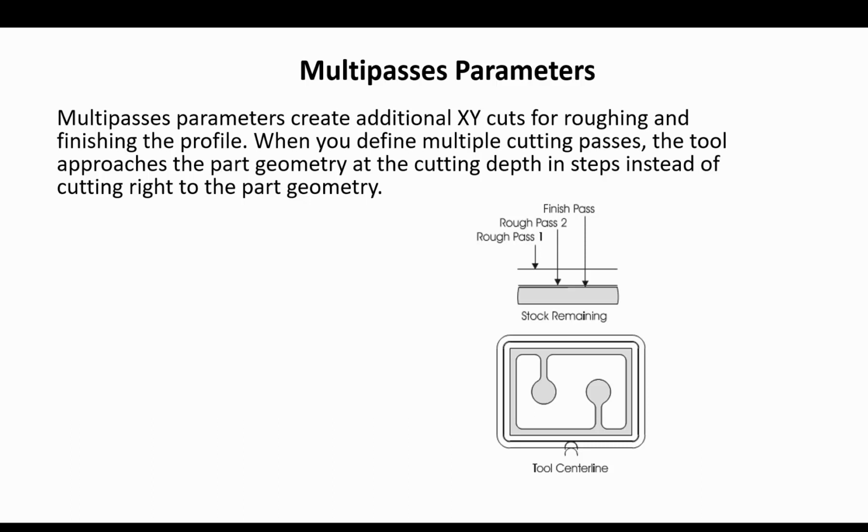A special case occurs when the number of roughing passes is set to 1. In this case, the rough spacing value is ignored since the rough spacing is established by the finished pass spacing. It is recommended that you set the roughing spacing taking into consideration how much stock needs to be removed.